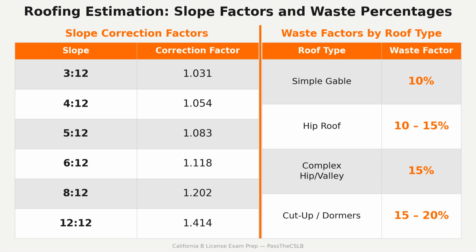On the upslope face of the chimney, when the chimney width measured perpendicular to the slope exceeds 30 inches, a cricket, also called a saddle, is required. A cricket is a small peaked structure built against the upslope chimney face that actively diverts water and debris around the obstruction. Without it, a chimney wider than 30 inches creates a pooling zone that produces a slow-motion warranty claim.